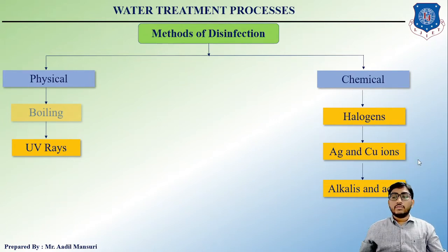Microorganisms can survive in a specific pH range, usually 6.5 to 7.5, and they cannot survive in a too highly alkaline or too highly acidic environment. So when lime is added to water, it can kill the microorganisms due to the creation of alkaline conditions.